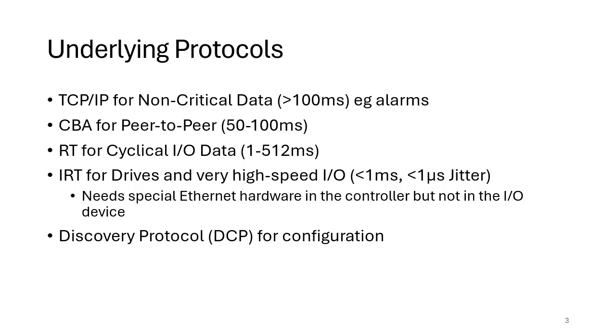Now, interesting with IRT, you need special Ethernet hardware in the controller to make sure that the data is sent at the right time, but you don't need it in the I/O device. So IRT is normally more specialized, but RT, CBA, TCP/IP, they can all use standard Ethernet.